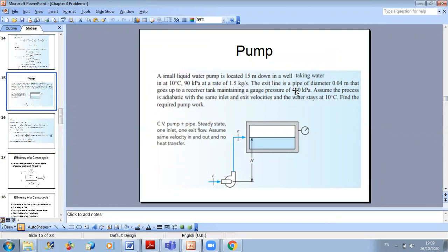Look, it is true that, as you are saying, the pressure is different, so of course the volume will vary a little bit. But because it's a liquid, we can see it together. We can search for it. The variation in V is very small. If you go to the thermodynamic tables, you can demonstrate that the difference is really small. This is why I can make the assumption that delta H is V delta P. And if you want, let us verify it together.